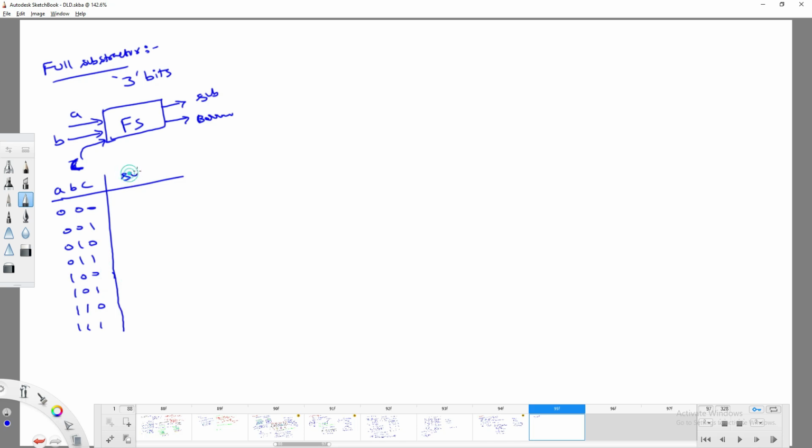So finally, my subtraction value: when I'm trying to do subtraction for the third bit, whether I have to take the borrow or not, right? When you are trying to do it between 2 bits, you can directly know, right? So now try to observe. I am trying to perform subtraction over 3 bits, so there is no borrow required, and the subtraction is 0. When you are trying to perform a minus b, 0 minus 0 is 0, there is no problem. But 0 minus 1, you require to take the borrow 1, and its subtraction is 1.